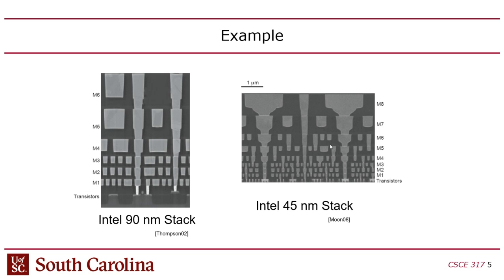Now obviously that's no longer the case, but Intel has a philosophy where they don't change their instruction set. So when you write code in Intel assembly language these days, you're literally using two-address instructions as a result of fabrication limitations from 50 years ago. It's kind of crazy. But anyway, as metal layers were added, instruction set architectures were able to take advantage of those metal layers to do things like 3-address instructions and pipelining and all the other neat stuff that you can do in an architecture now.